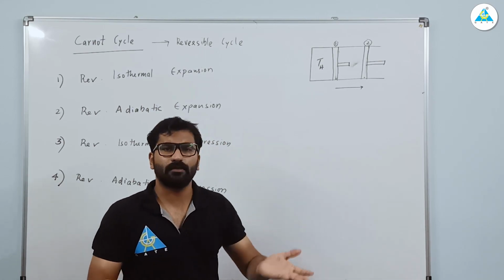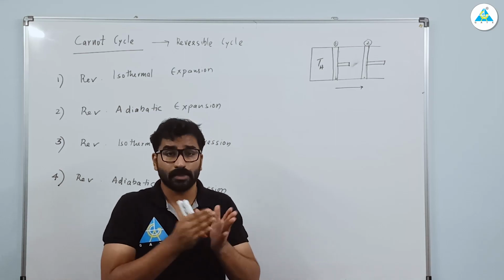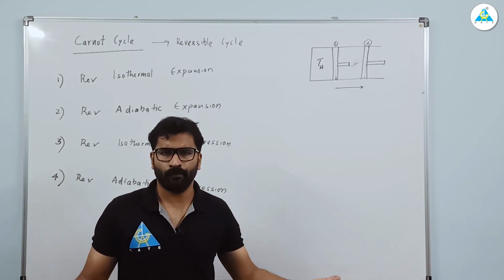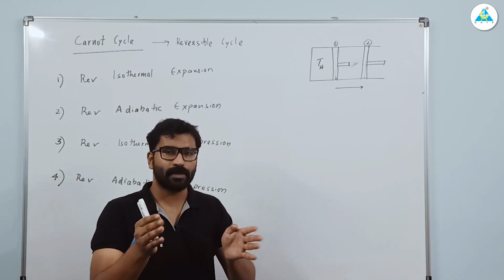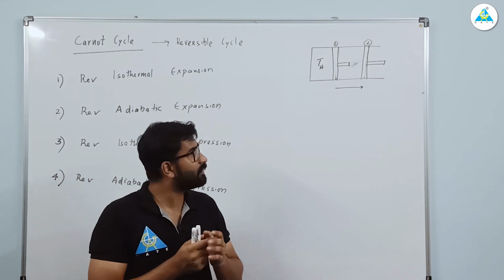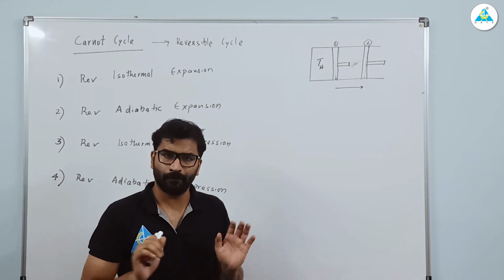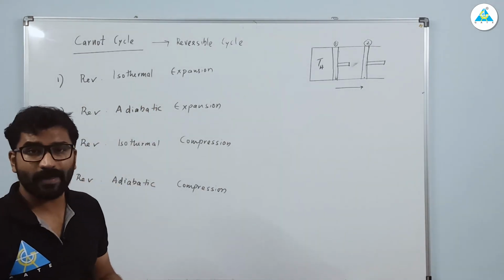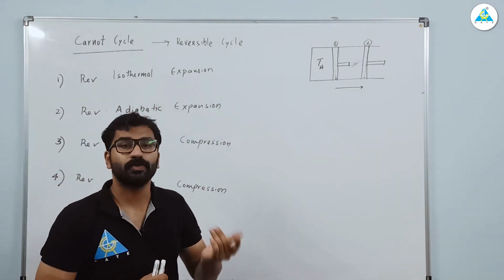And obviously we can say it is a frictionless piston. So the process is reversible, or we can say it is close to reversible. Clear? So it is a very slow expansion. Now when it is a very slow expansion, what will happen? The temperature also will decrease very slowly, right? But it should be a reversible isothermal expansion. That is, we don't want the temperature to change.